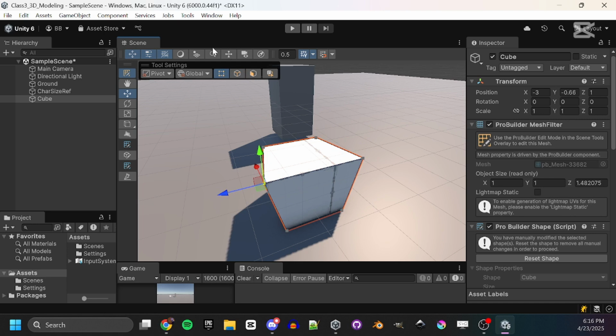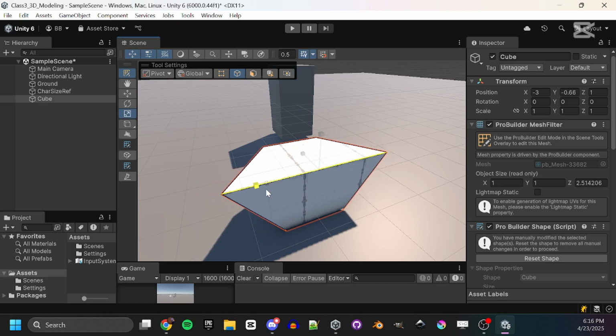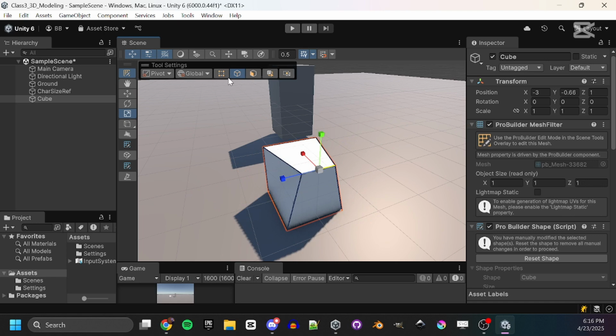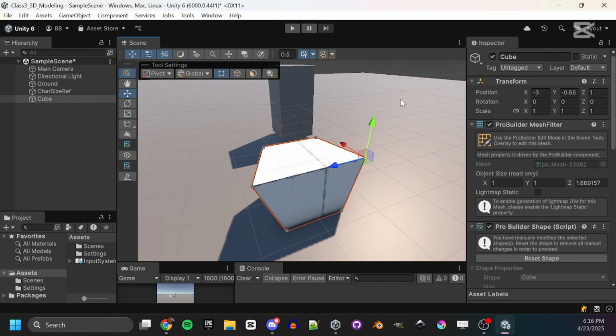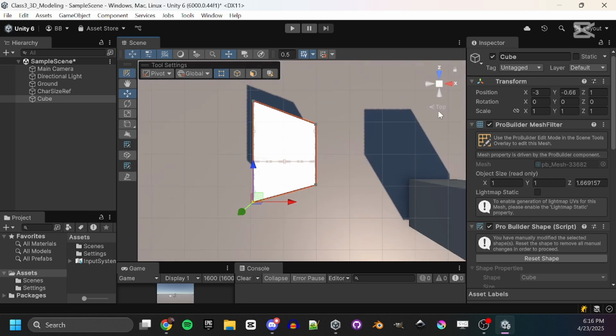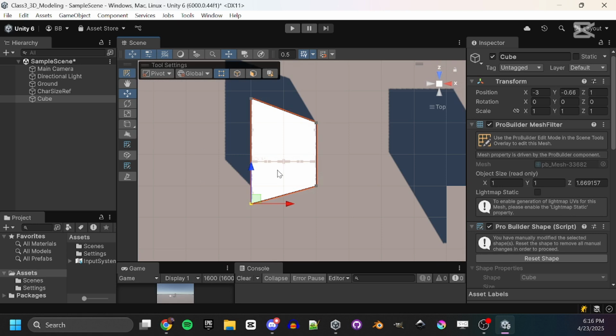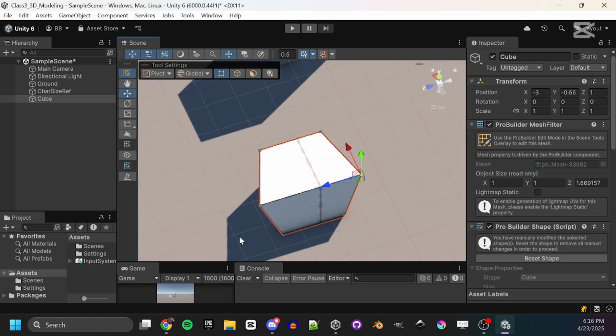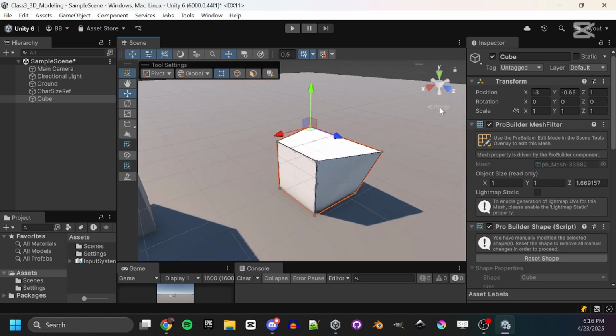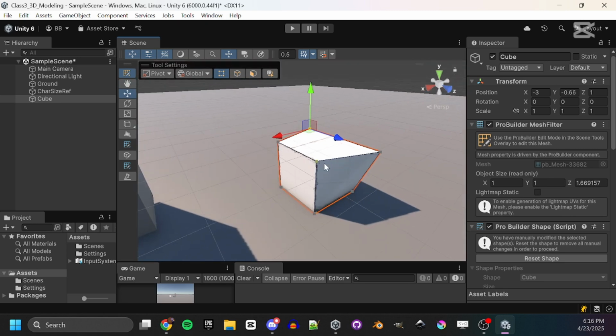So it's more than just what you could do with grabbing vertices and adjusting them. But what's nice about scaling an edge like this is that it's going to do it evenly in both directions. And so you keep your symmetry much easier than if you're trying to, all right, I grab this one and drag it out, and then I try to drag this one out about the same amount. Yeah, you could do things to try to make that work. Oh, I could go into a top-down isometric view and try to roughly line myself up with the grid. But just like with virtually anything in computers, there's always going to be multiple ways to do something, and some are easier than others.